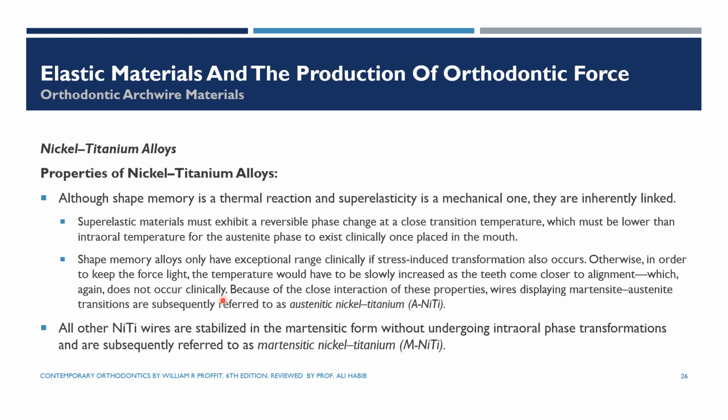So A-NiTi includes both superelastic wires that respond to stress and heat-activated wires that respond to heat. All NiTi wires other than the A-NiTi are called M-NiTi, because they are stabilized in the martensitic form. This is the original NiTi that we had, without undergoing this intraoral phase transformation. It was the original NiTi because at that time they couldn't express this transition from one phase to another.